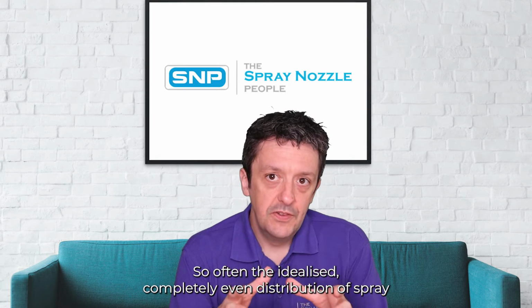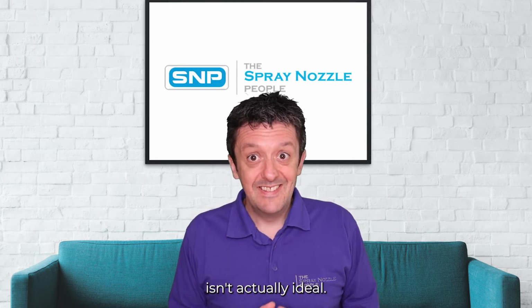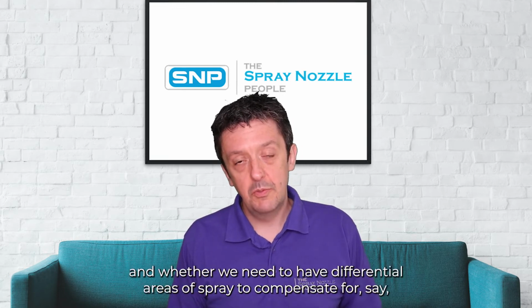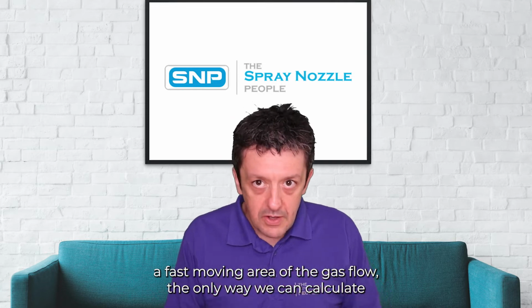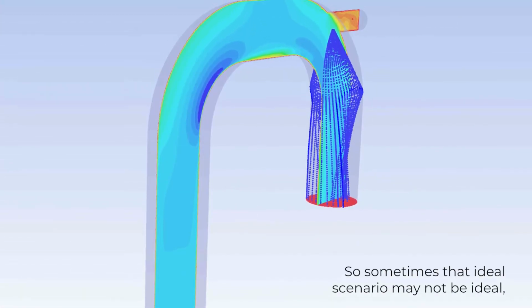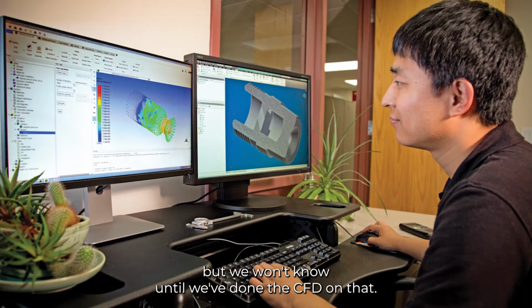So often the idealized, completely even distribution of spray isn't actually ideal. The only way we can work out whether that's the case, or whether we need differential areas of spray to compensate for, say, a fast-moving area of the gas flow, is through computational fluid dynamics. So sometimes that ideal scenario may not be ideal, but we won't know until we've done the CFD on that.